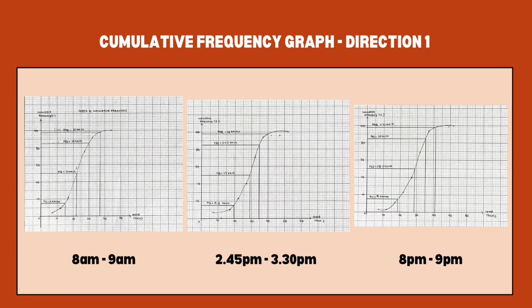So from this cumulative frequency graph, we will obtain 15 percentile, which reflects the behavior of slower moving vehicle. 85 percentile reflects the speed which the majority of vehicles operate under free flow condition, while 98 percentile shows the faster speed.